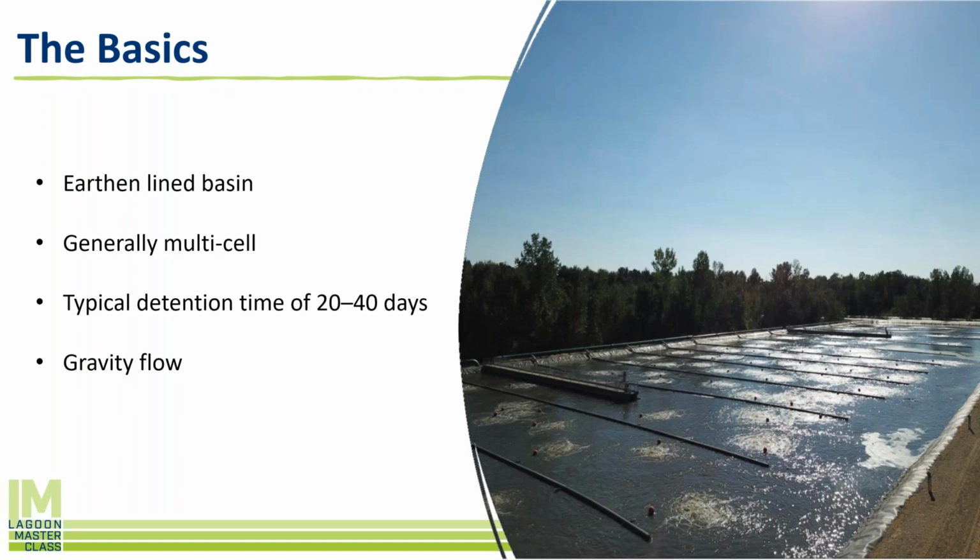So we're gonna start with a 30,000 foot view. I know for 99% of you, you understand this, but I wanna get a baseline of information down and build from there. So we all know that a wastewater lagoon is an earthen-lined basin. It might have clay, it might have earth, and then an HDPE liner, but very, very rarely, and I'm talking like 1 in 1,000, do we see a concrete-lined basin. We're typically using the earth.